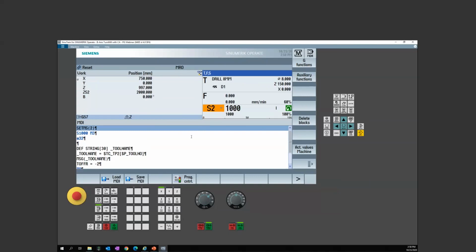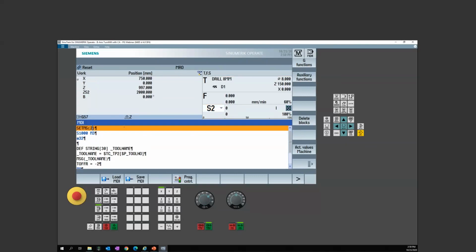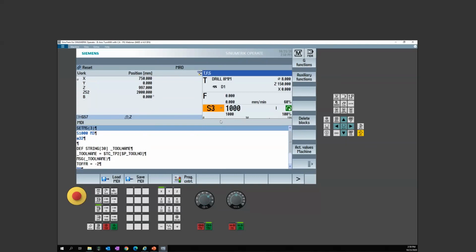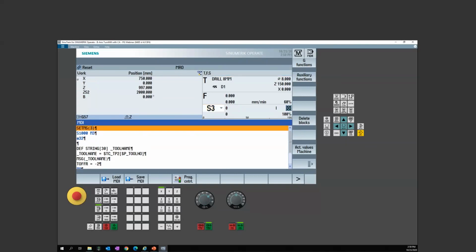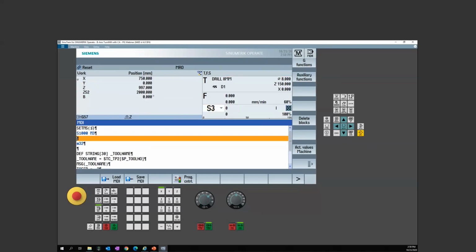The tricky part, and usually why I don't have posts do this, is now it's asking for a little bit of logic for the post. And what happens is, so now number 3 is there. So let's say for argument's sake, I wanted my main spindle to turn on, but I was also going to have a tool spinning because maybe I was going to run an end mill while I spun the C axis.